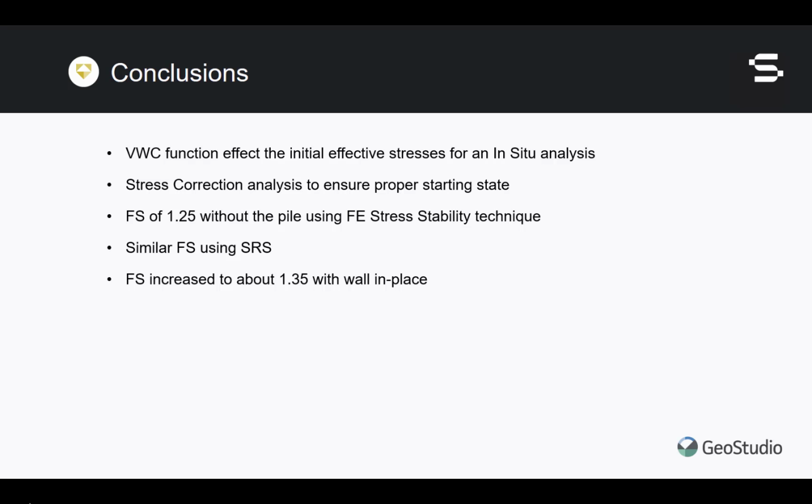We also saw that introducing the wall into the system, which carries the load as deformation occurs, restricted the amount of deformation, which was witnessed not only in the graphs of normalized domain stiffness and vector norm of displacements, but also the lateral displacements at the pile wall location and the toe of the slope.